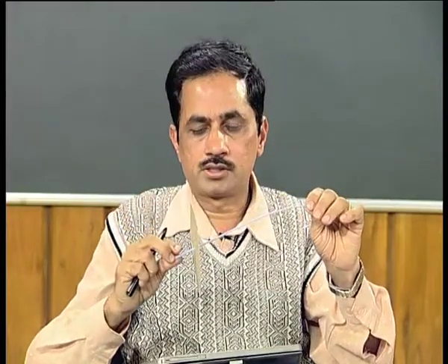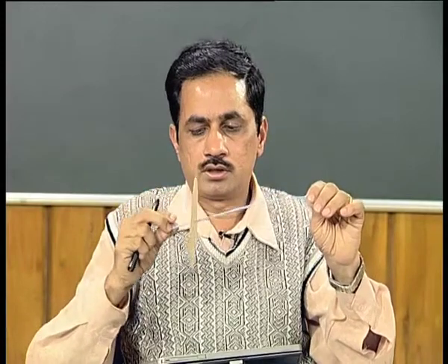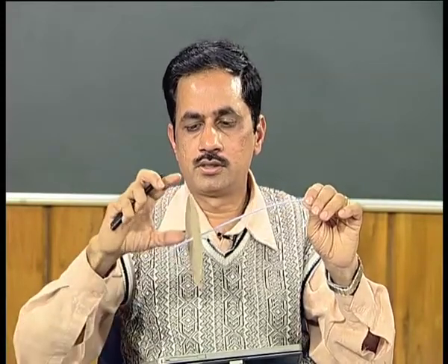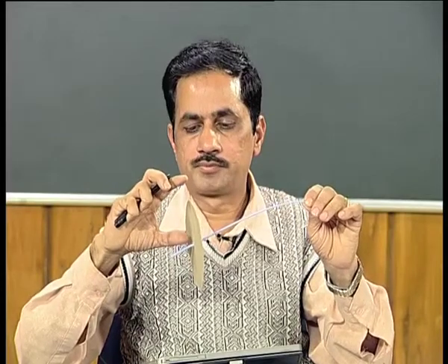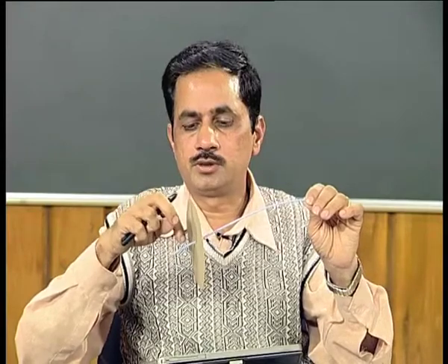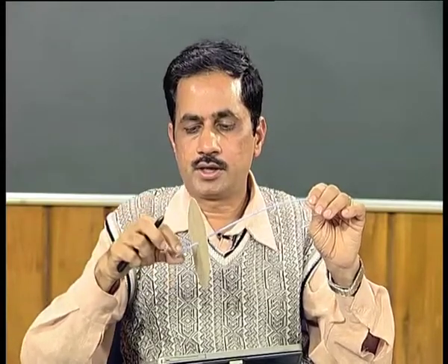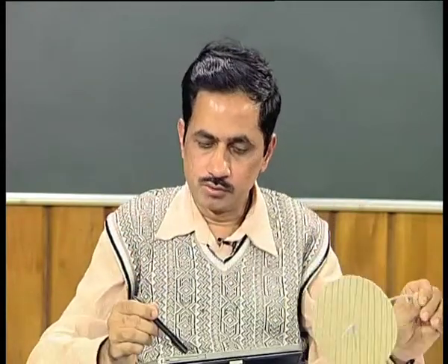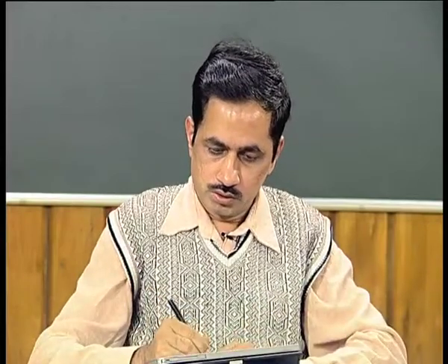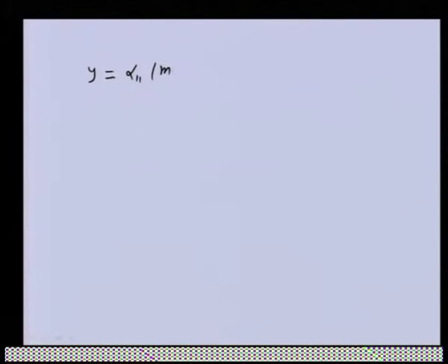So when the disc is coming here, its angular velocity is omega, and this is the y displacement. So, because of that, the centrifugal force at this particular extreme position will be acting downward, and the magnitude will be m nu square y. So, this will be nu square y plus alpha 12.